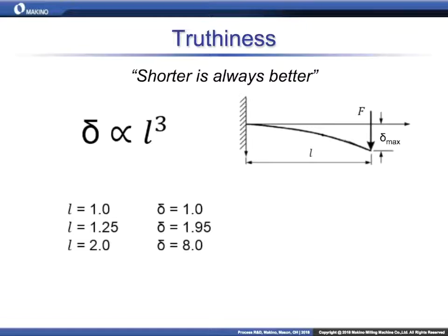Yes. Actually, the deflection. So let's say you had just a unit of 1 on the length and a unit of 1 on the deflection. We use that as our baseline. Let's say you increase the length by 25%, like what you have here, a length of 1.25. We've now almost doubled the deflection. We've gone to 1.95 on that level of deflection. Right. Just by 25%. Yeah.